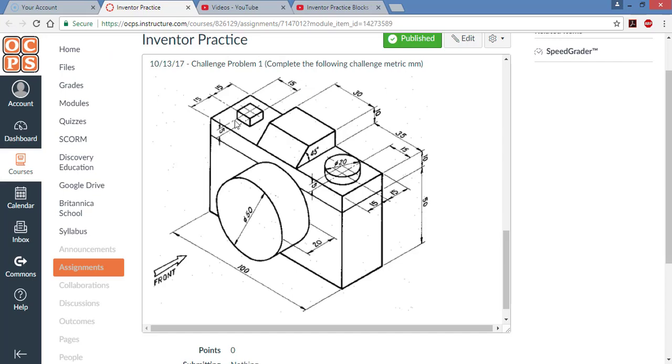Next, we'll go ahead and make the square, and we're going to make this circle here. Both of these are extruded up 5 millimeters, so we can make them simultaneously. We just need to know where they're placed. It's hard to tell, but the center of this square is actually 15 away from the edge, and the same thing applies with this circle. So I'm going to go ahead and make a square on this side, and the square is actually a 10 by 10 square, and the circle is 20 millimeters in diameter.